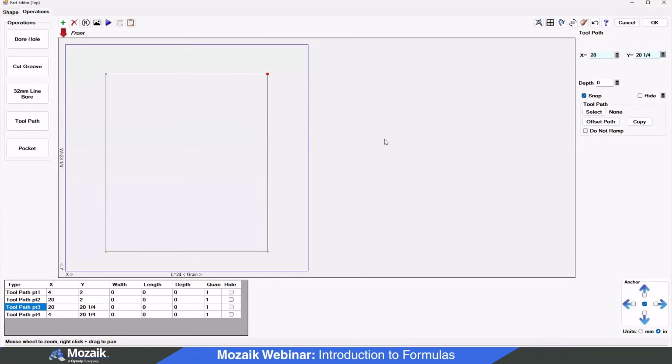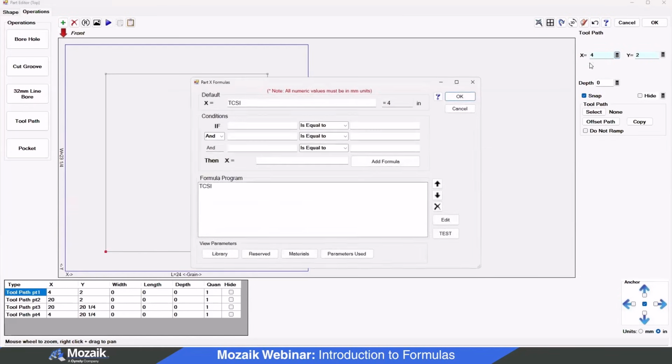I want to add now an automatic sizing. So let's say this cabinet was to shrink down past, say, 12 inches, and I have my rails set too large, so that they're going to collide with each other. So I want to set a kind of fail safe and just make sure that my X points are going to automatically size to an appropriate size. So selecting the node here, I'm going to select the X, and we're going to add an if statement.